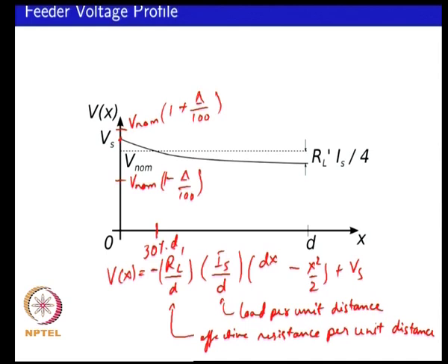So, tap changer would do it for all the feeders at the substation. You could also have a series voltage regulator, one for each line. These regulators can be located either at the substation, or if you have a really long feeder, it could be further down the feeder to get your required voltage to be within an acceptable range.